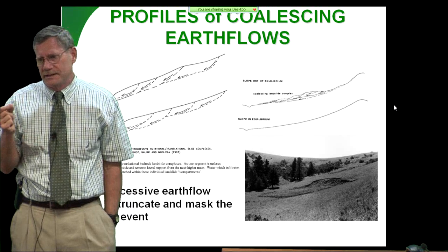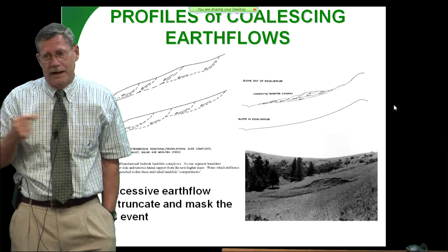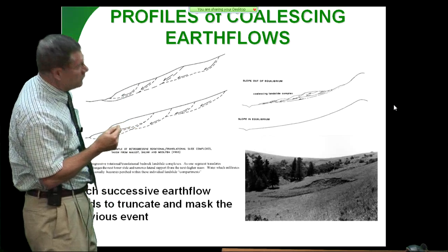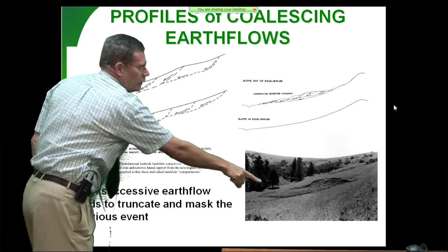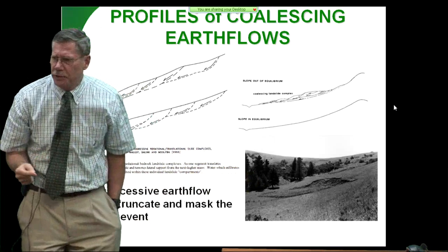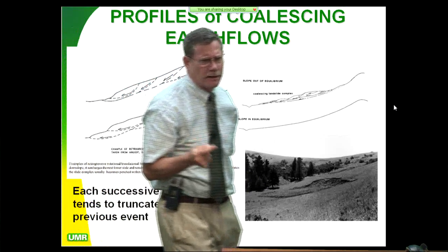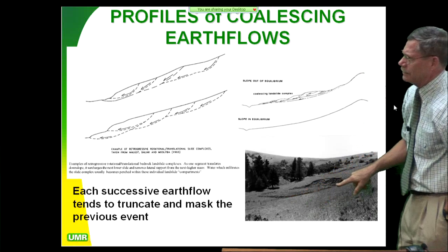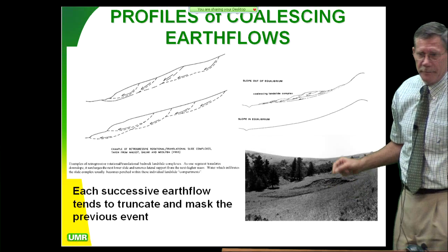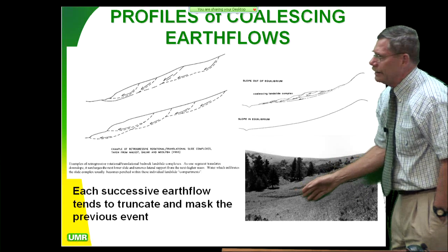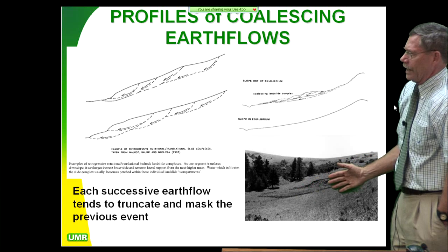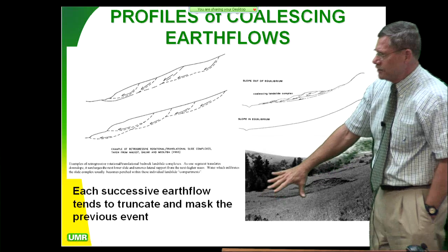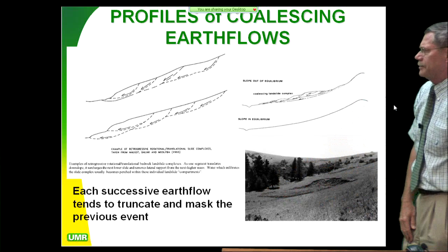Those are the things that are going to drive you nuts in life, because the patient comes in and they're not coughing when they come to the office. You go out there, you're looking around and you're going, I don't see any water. Do you see any water on that slope? There's not a tree, there's not a bush, there's not a cattail, there's nothing there. It's a water-loving plant. But this is at St. Mary's College. When I hogged this thing out, there was a spring right there. Little bitty spring. And so this is all clay, and the clay liquefied, mobilized, and moved downslope till it had sufficient drainage, engendered some shear strength, and it stopped.